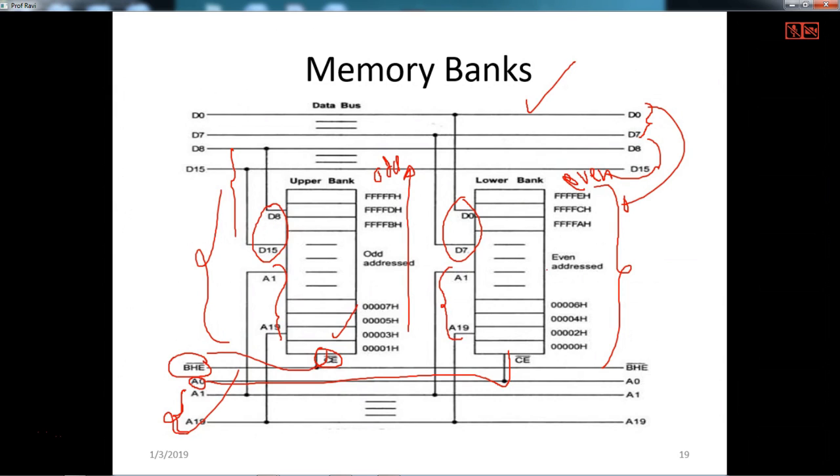And now this address lines A1 to A19 and this address lines A1 to A19, you can give to an address decoder. You can connect an address decoder in between to identify, based on the memory mapping, which address you can use. But this is the fundamental memory interfacing concept. Is it all right?